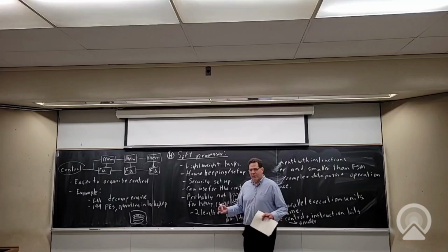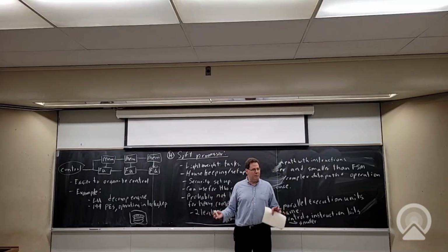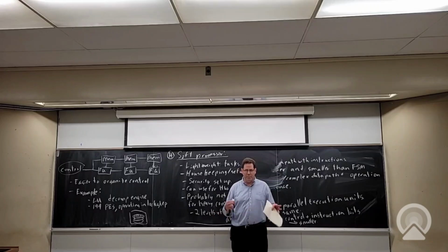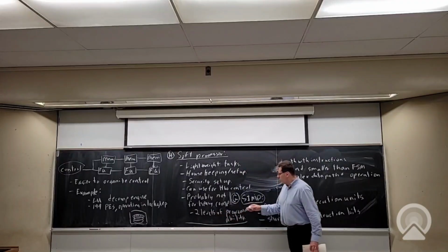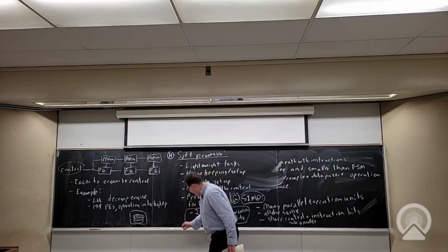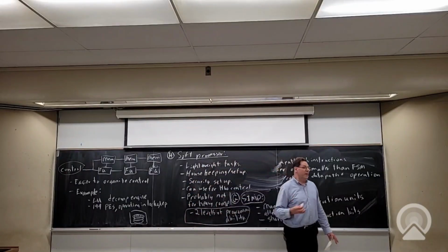Now what you get for programmability is that you get to market much faster, and you avoid very large NREs. The cost of a completely custom chip, depending on the process technology, is maybe $30 to $100 to $200 million. So if you have programmability, you avoid that. But there are 2 levels of programmability, and the second level doesn't buy you that much.